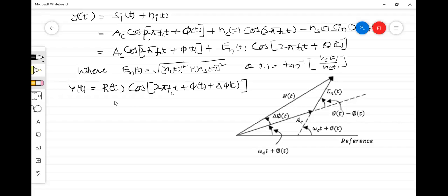The amplitude limiter will maintain the amplitude constant, as in an FM signal, because an FM signal carries the information in the form of angle variations or frequency variations, not in the form of amplitude variations. So if there are any such variations due to noise or other factors, they can be eliminated by using an amplitude limiter. Because of this factor, FM is inherently immune to noise.